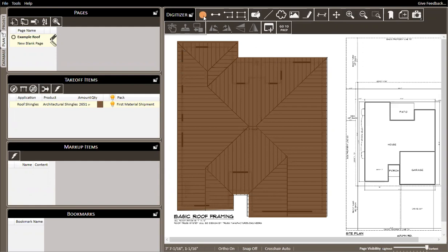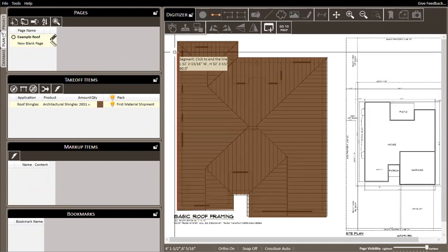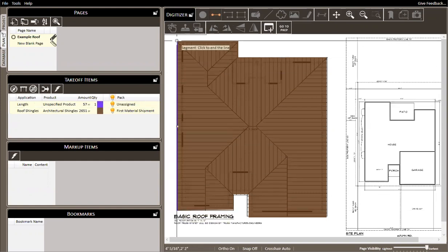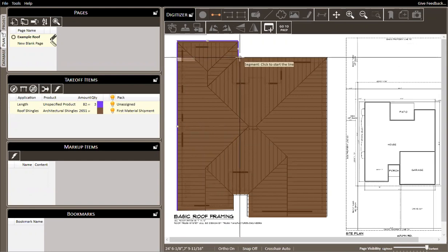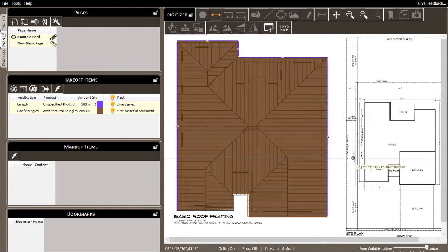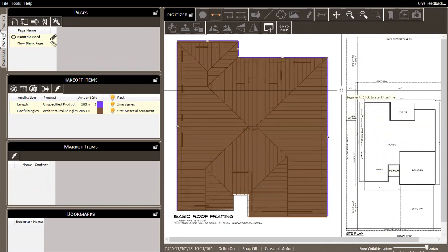So for example, let's say that I want to capture, I'm going to go to the gutter side of this roof here. I'm going to trace how much linear footage of starter shingle. As we start up the side of this roof here, we need to have a starter shingle row. But as I look at that, I might realize, oh, you know what? That dimension there, that linear footage that I'm measuring there, not only does it apply to the starter shingles, it also applies to the edge flashing that I'll need along that edge.